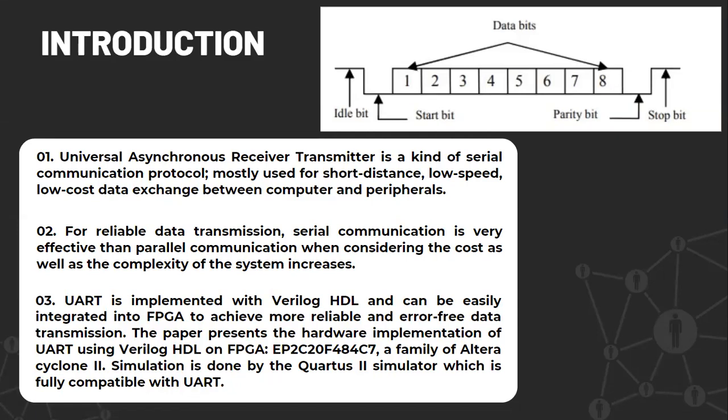The UART allows full duplex communication in a serial link, thus it has been widely used in data communication and control systems. In actual application, usually only a few key features of UART are needed. The basic UART communication needs only two signal lines, RXD and TXD, to complete full duplex data communication. TXD is the transmit side, also known as the output of UART. RXD is the receiver, the input of the UART. UART basic features: there are two states in the signal lines, using logic 1, which is high, and logic 0, which is low, to distinguish respectively. This was the meaning of the above diagram.